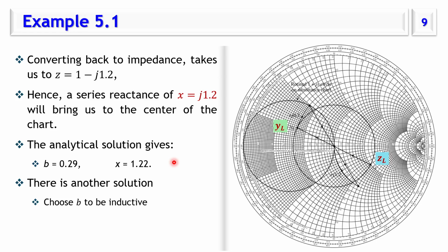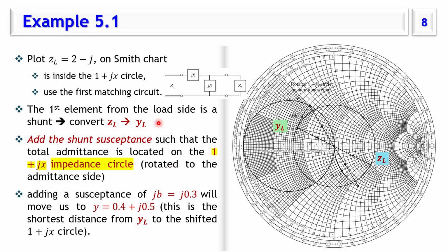So the Smith chart is very good for visualizing, or as I said, arranging your thinking procedure, because you can draw and say, okay, now I'm here, I have a certain load impedance. After adding the first element, I want the input impedance at this point to equal 1 plus some j value.